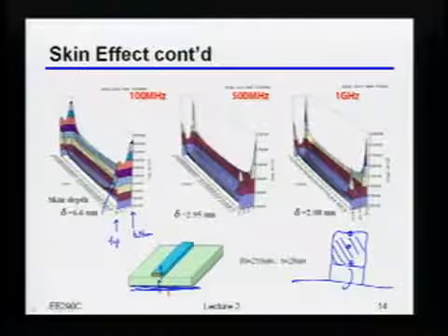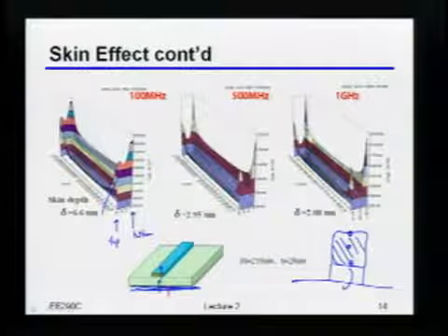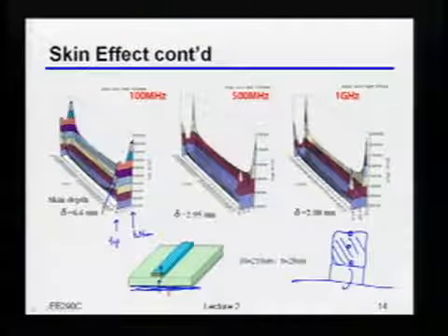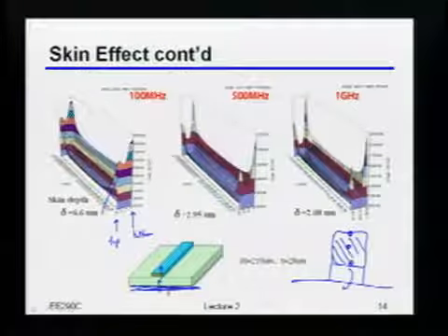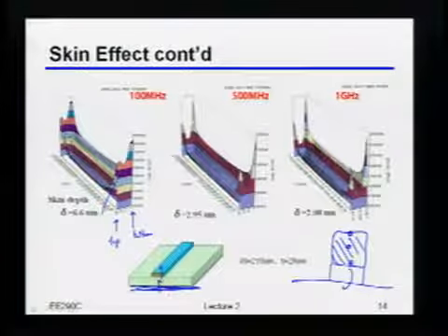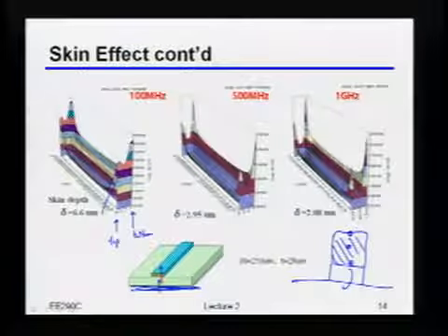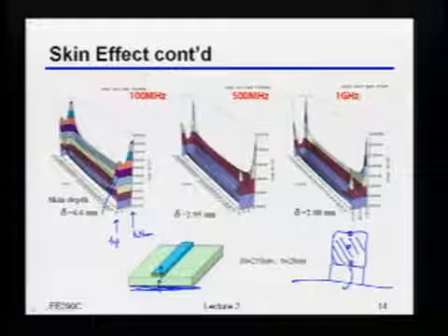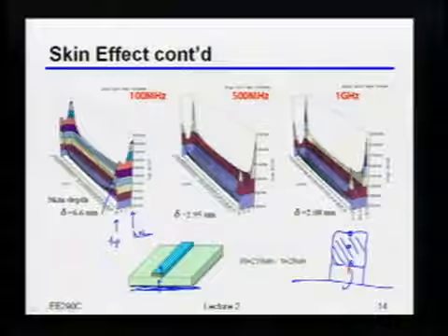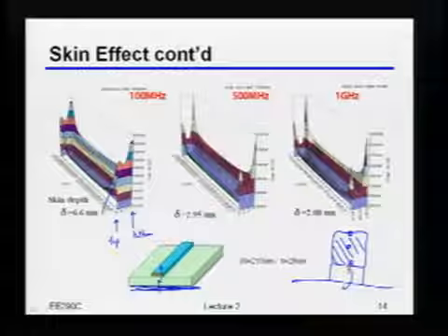Is that mainly because the current is flowing in a different direction, so the mutual inductance will be a minus term? Then if you get closer, the minus term is larger, right? So which effect are you trying to explain? I'm asking why it's getting closer to the ground plane. There's probably a much better electromagnetics way of explaining it, but intuitively the easiest explanation I know of is that you're trying to make that net impedance as small as you can. And at high frequencies, inductance matters a lot, right? So that means the current gets pushed as close together at the surface as it can, just to minimize the area of that loop.